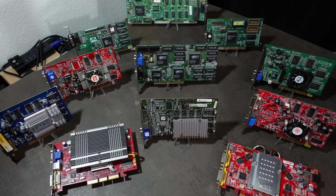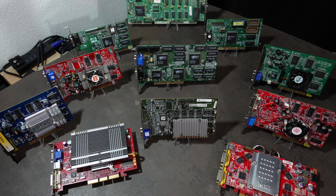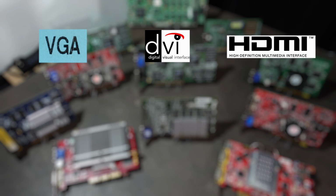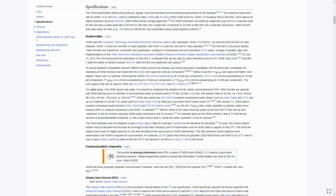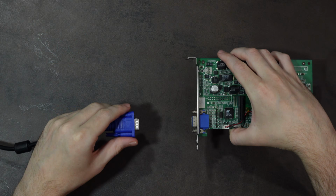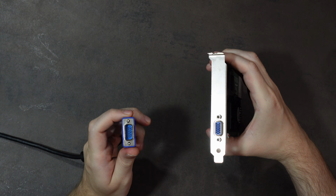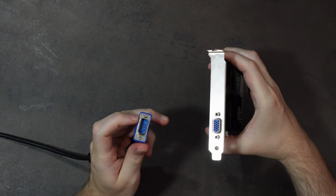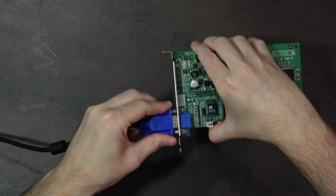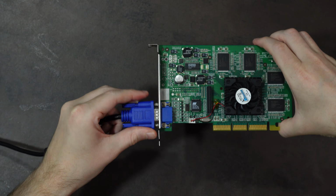First of all, it's important to understand the basic characteristics of VGA, DVI and HDMI. All three of these terms are actually graphics or signal standards, but they are also used for the corresponding ports. However, other signals can also be sent using the same connectors, which can make it a bit confusing. Let's start with VGA, or let's say analog signals which are sent via a 15-pin connector called D-sub, or more precisely DE15, which most of the time got a blue plug.